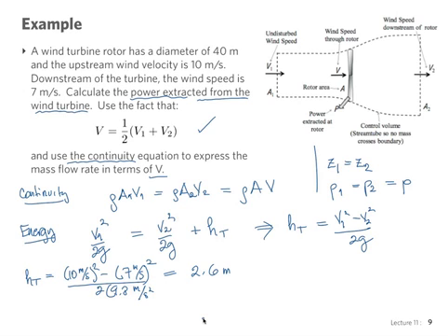So what now? See? The power equation, very good. We just learned to use the power equation, and we need to be able to write that down and see if we have everything. So for the power equation we have W dot equals, let's write it as gamma Q HT, and we can calculate Q because we have area, velocity and rho. Let's write it as rho g, and this is just A V and the turbine head. So now the area we can calculate.